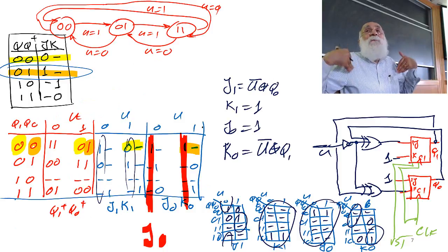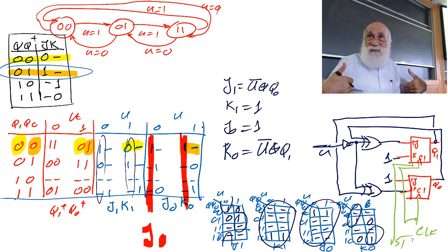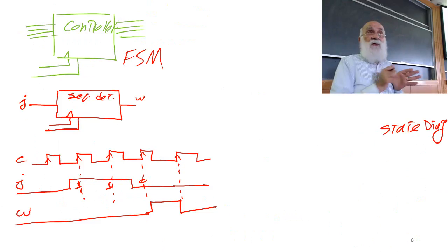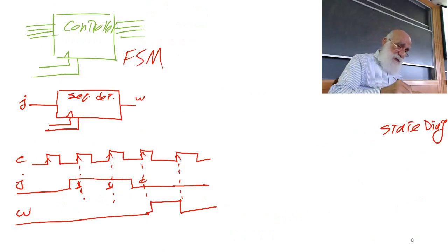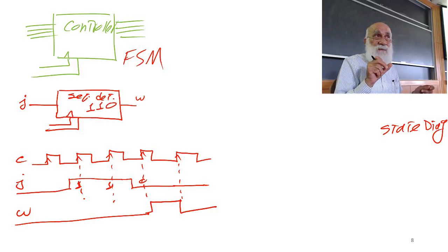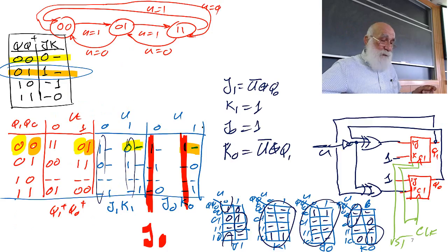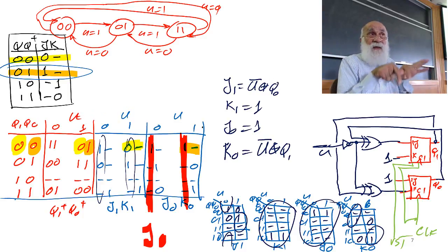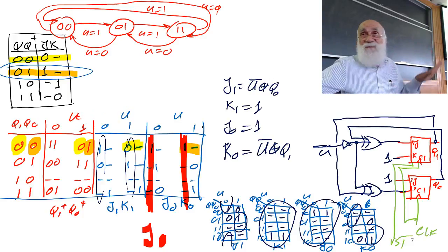So the key thing is, if I'm able to turn my circuit into a state diagram, if I'm able to turn this description, see, I already have the description for you, right? The sequence detector is detecting sequence 110 on its input. If I'm able to show you a state diagram detecting this, then the rest of it would be very similar to this, very mechanical. Actually, much easier than this, because here I did JK flip-flop. I'm not going to do JK flip-flop throughout the course anymore. D flip-flops I'll do.